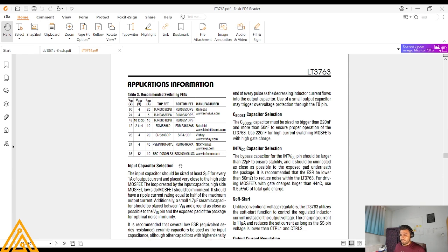One of the things that I really like is using MATLAB. Whenever I work with these kinds of formulas, I try to utilize them in MATLAB. After writing them in MATLAB code, I choose the MOSFETs that are available and put the variables in my formula to calculate the minimum loss that I could get.